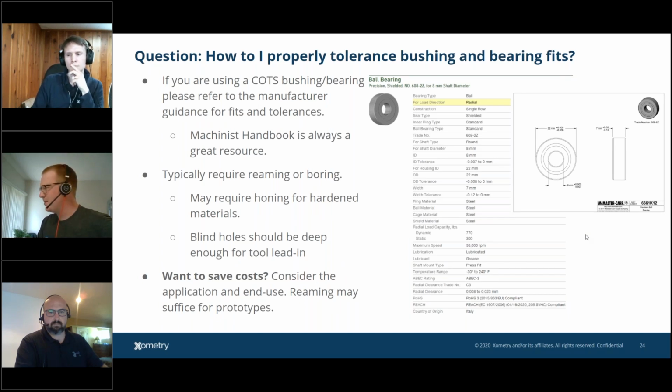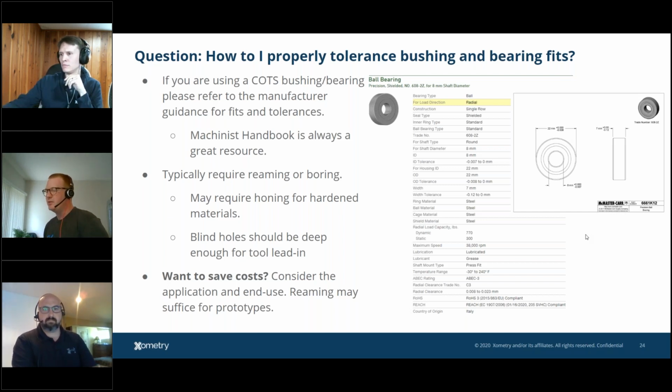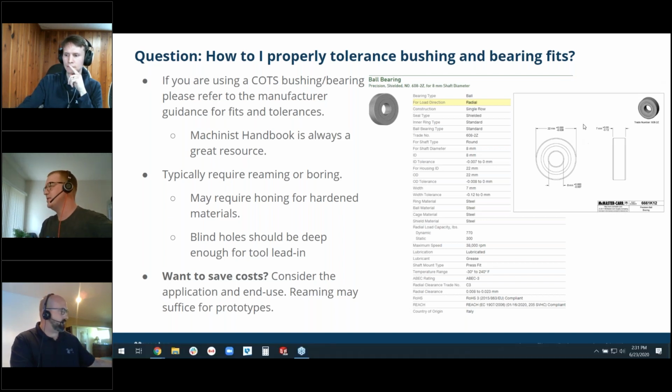And it's a really good question. It's kind of Pandora's box. You have to be careful with it, because in general, the manufacturer for the particular bearing or bushing that you're going to use will have an applications guide where they will give you not only information about the lifetime and proper load conditions for the bearings, but also guidelines on how exactly mating parts should be manufactured.